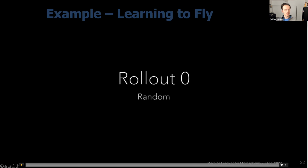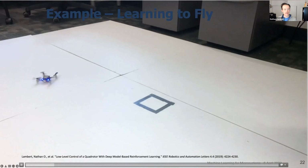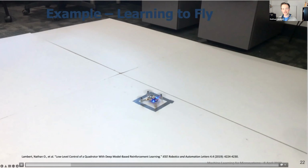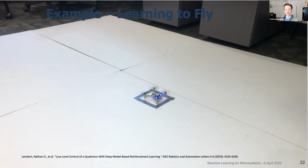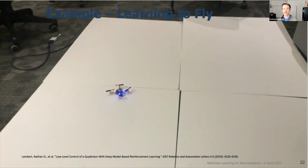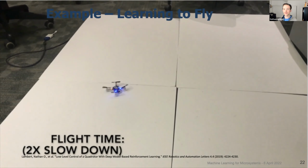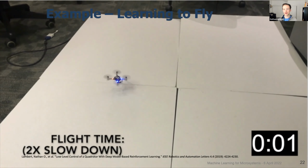And this is actually a video that you all may have seen in the past, but what you see is that the quadrotor starts by taking these random trajectories where it can barely do anything at all. It'll flip over instantly, and that's by design. And then we iteratively retrain this dynamics model of the world to get an understanding of the robot. And then over time, the cost function is achieved. So this is a simple proof of concept where we have a robot, we can do trial and error in the real world, and we can get interesting and compelling results.